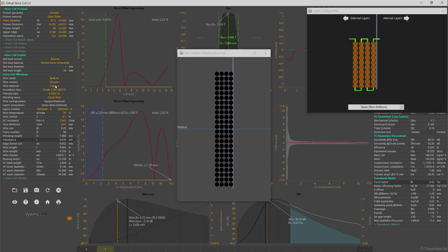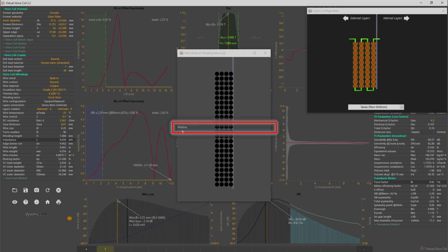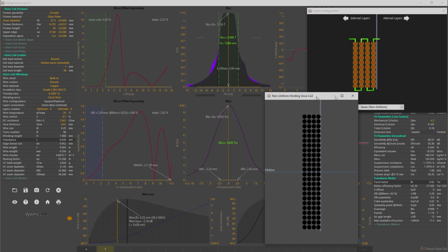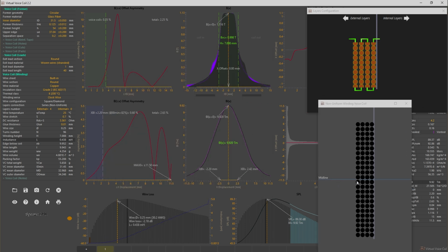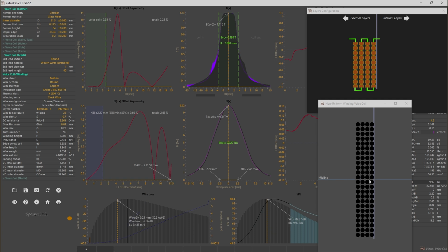The displayed wire shape follows the selected wire section. Now we can recall the record number 1. Horizontal midline identifies the winding symmetry plane. It also represents the X offset coil position along the BX magnetic gap. It could be useful for an engineer to check if the midline is in the wire center or between 2 turns.